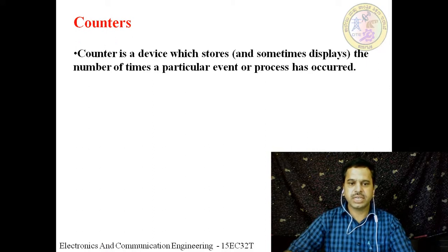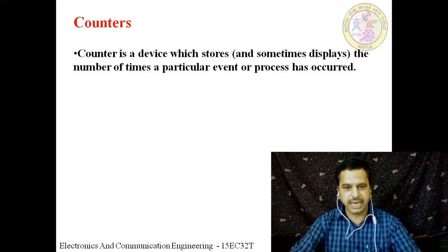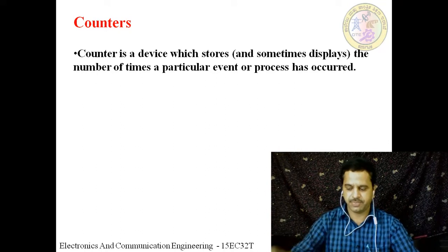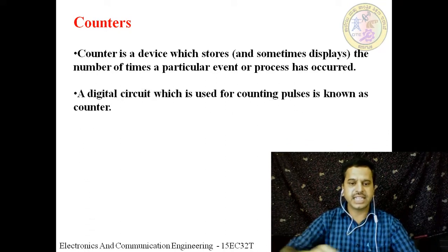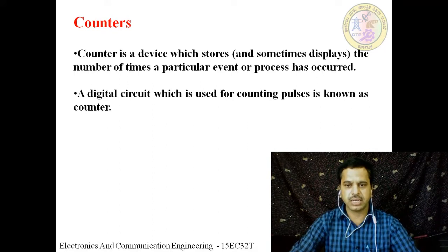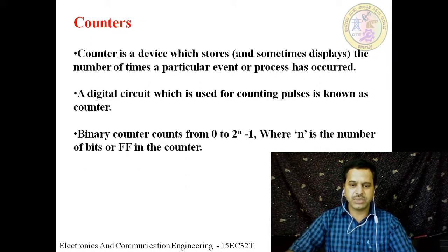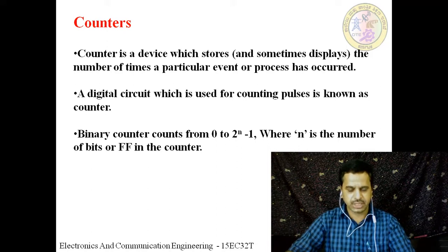Counter. What is a counter? A counter is a device which stores and sometimes displays the number of times a particular event or process has occurred, or a digital circuit which is used for counting pulses is known as a counter. For example, a binary counter counts from 0 to 2 power n minus 1, where n is the number of bits or flip-flops in the counter.